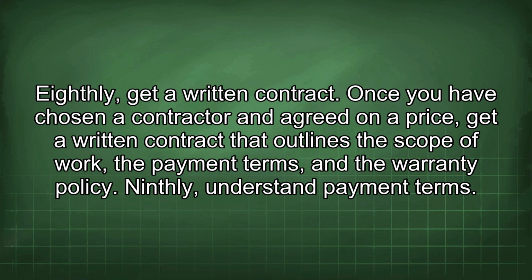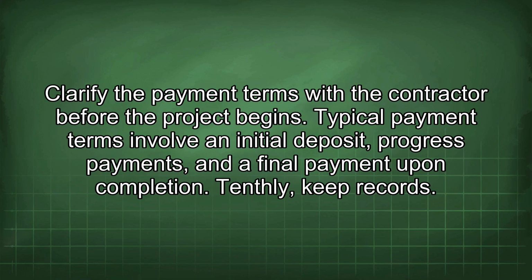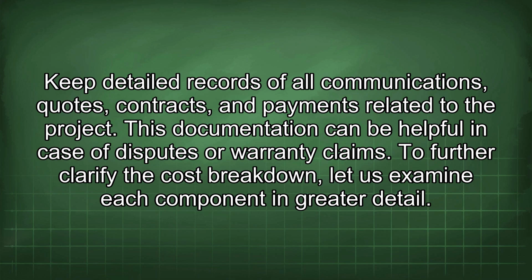Ninthly, understand payment terms. Clarify the payment terms with the contractor before the project begins. Typical payment terms involve an initial deposit, progress payments, and a final payment upon completion. Tenthly, keep records. Keep detailed records of all communications, quotes, contracts, and payments related to the project. This documentation can be helpful in case of disputes or warranty claims.